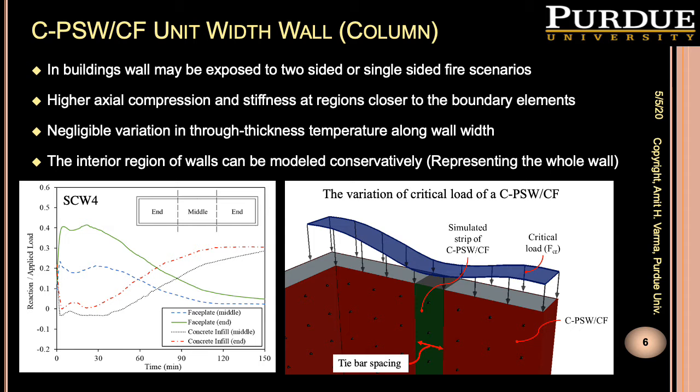The normalized axial load of the concrete infill and faceplate in the middle and the end regions are compared in the figure on the left. The axial reactions were almost the same at ambient temperature for both regions. At the beginning of the analysis, the model underwent thermal expansion, and the axial force in the concrete infill dropped, and most of the applied load was transferred to the faceplate.